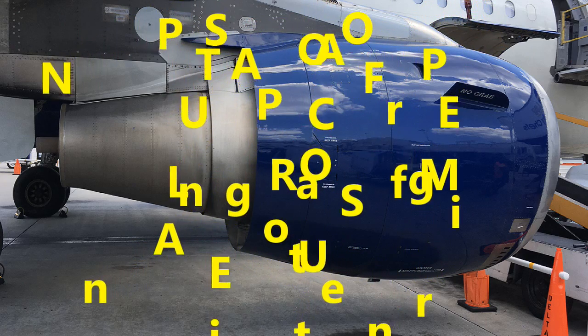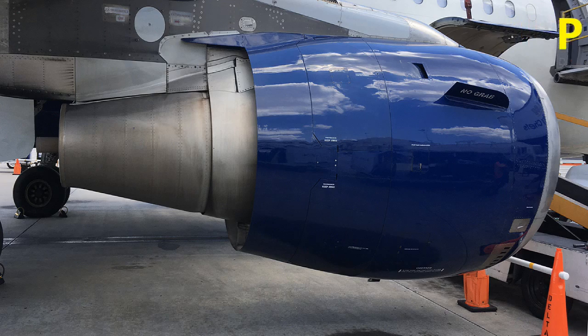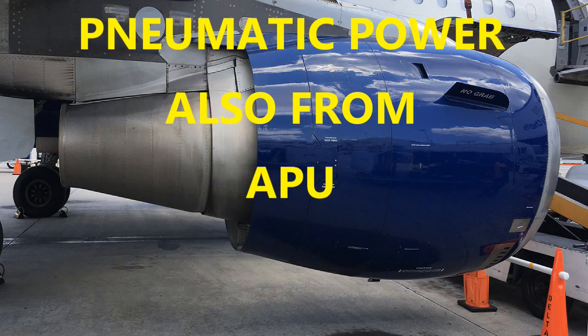It was a combination, and it depended on that combination how much could be supplied at certain altitudes. Here, the pilot can switch the APU on, and it can give him what he needs at up to 20 to 25,000 feet, so it can definitely be used in flight. But mostly it's meant for the ground: if you're doing ground maintenance and need the APU for power, you certainly have that as a ground air supply.